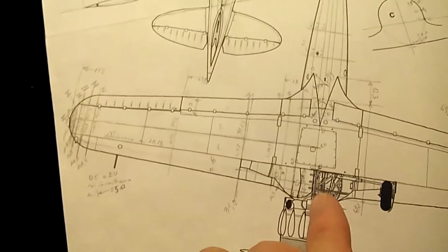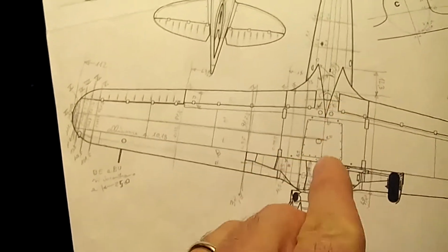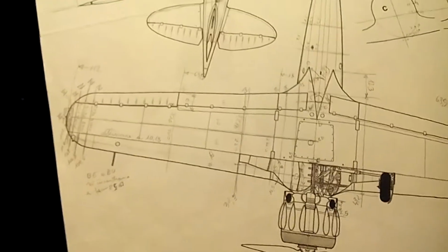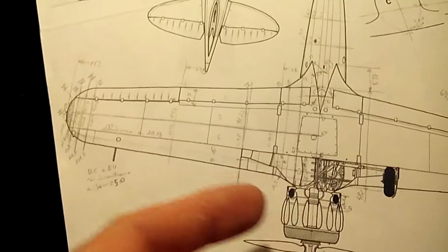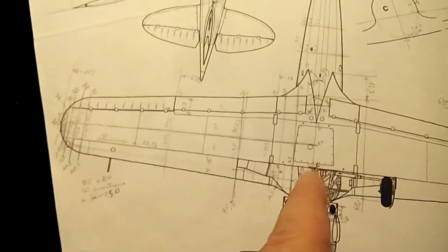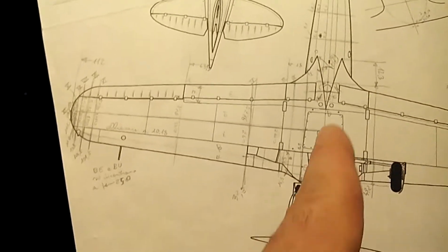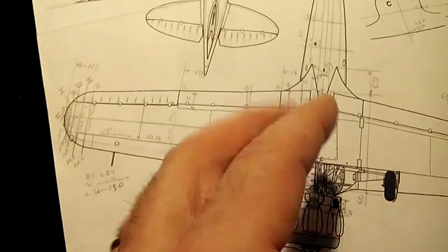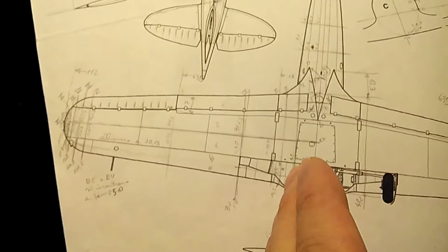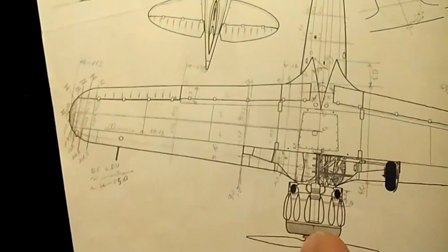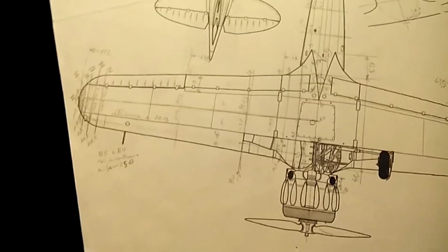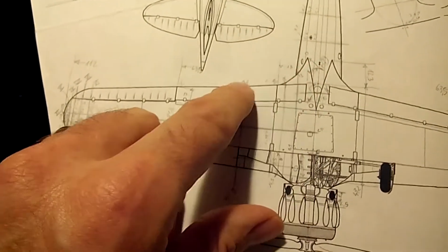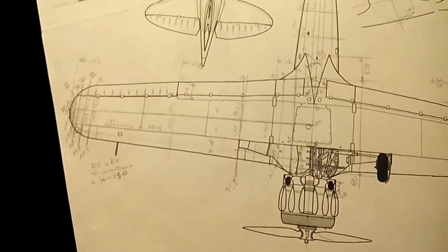Okay, the first section in this case is at the middle datum of the plane. Not all planes have this condition, but it's better to leave at least one section inside the fuselage, which will be helpful both to better join the inner section to the actual side of the fuselage, and eventually to draw the extensions of the fillet in the wing root.